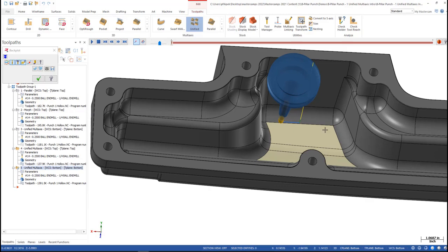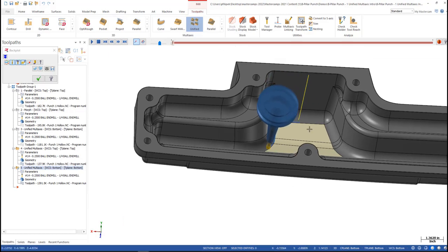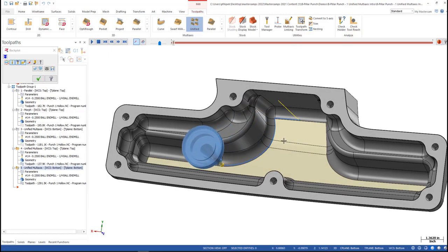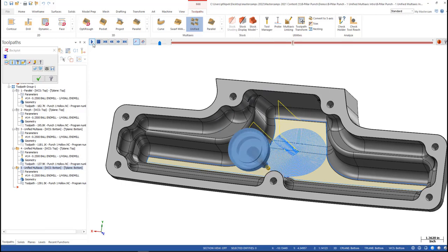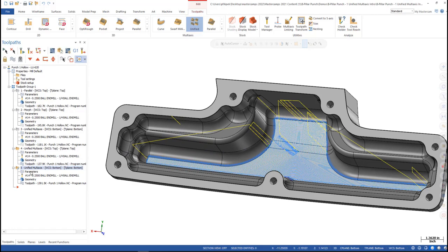wherever that ends, you have a scallop along that edge. So what that does is, see how I can get a toolpath to go all the way along this edge first, and then it starts to spiral out from there. So here goes my parallel spiral motion working its way out. Now I'm going to have a nice clean edge along there that typically you had to run a curved toolpath along, or your deburrers took care of that. So that's kind of a nice little feature to be aware of.